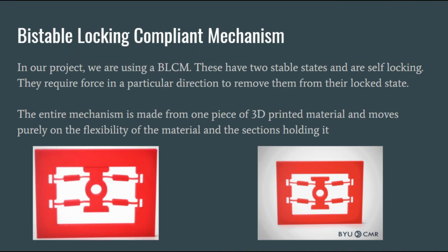Bistable mechanisms are mechanisms that have two stable equilibrium positions within the range of motion. That is, they have the ability to stay in two positions without any power input. Because of this ability, bistable mechanisms have applications in many devices such as switches, valves, closures, and clasps. Compliant bistable mechanisms are a particular class of bistable mechanisms which use deflections of their members to gain motion, rather than relying solely on traditional rigid body joints. Compliant mechanisms represent an elegant way to achieve bistable behavior because the flexible members allow both motion and energy storage to be incorporated into one element.